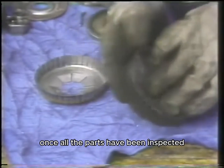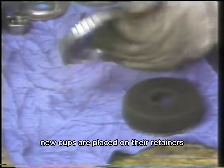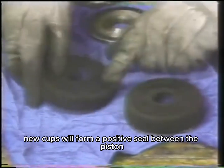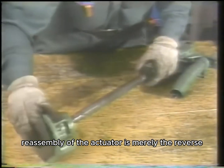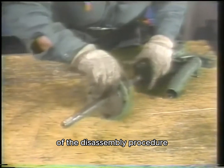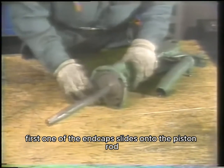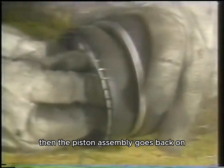Once all the parts have been inspected, reassembly can begin. New cups are placed on their retainers. The new cups will form a positive seal between the piston and the cylinder walls. Reassembly of the actuator is merely the reverse of the disassembly procedure. First, one of the end caps slides onto the piston rod and is placed in position. Then the piston assembly goes back on.